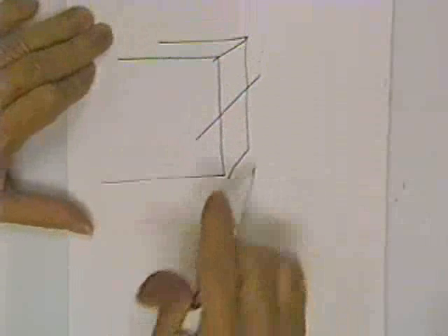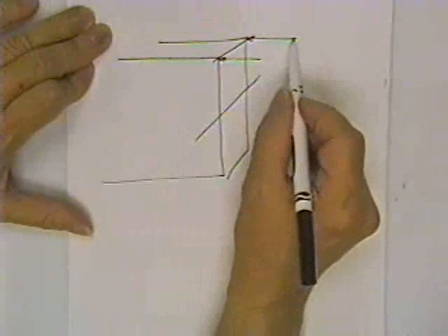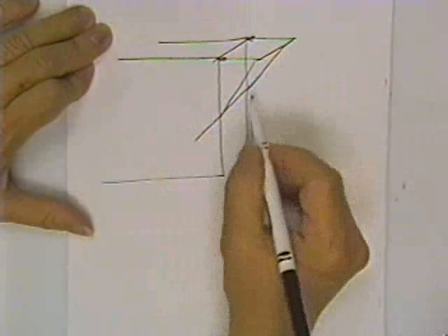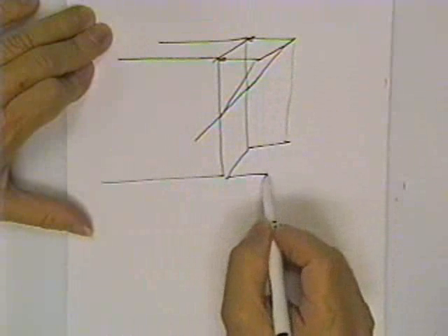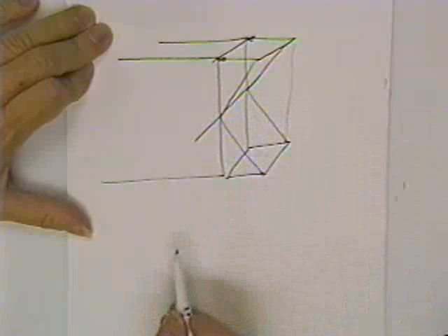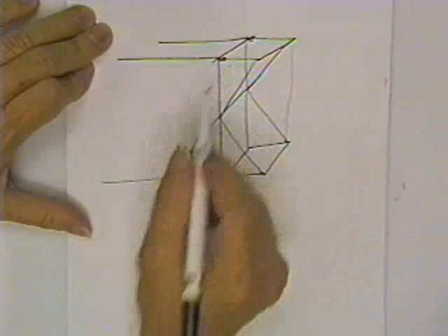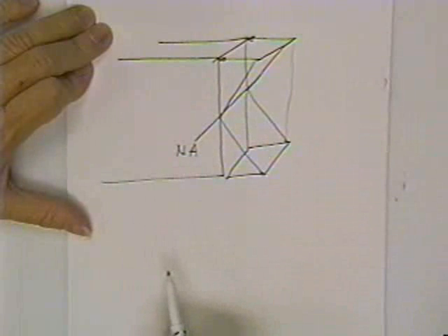I showed you that that beam will normally have compressive stresses on one side of the beam, and tension stresses on the other side of the beam, and they are distributed linearly from the neutral axis. They are maximum on the outside fiber. They're zero at the neutral axis.